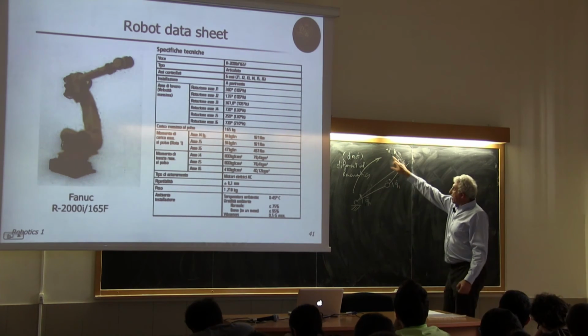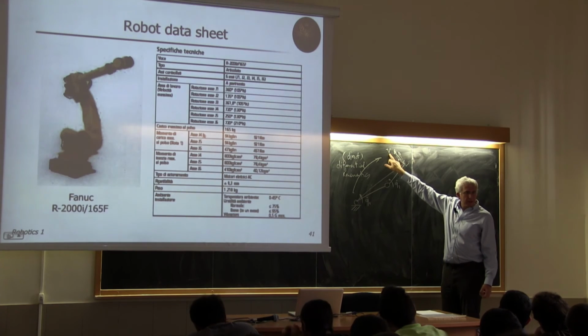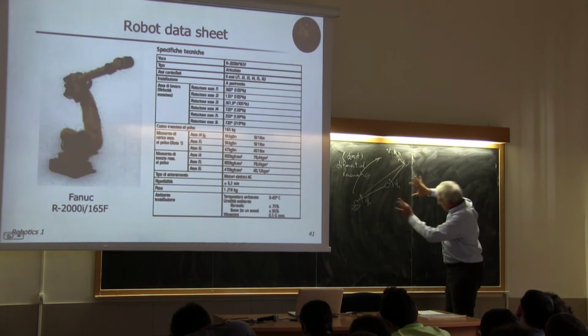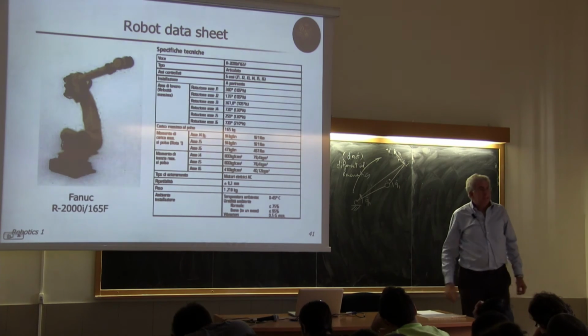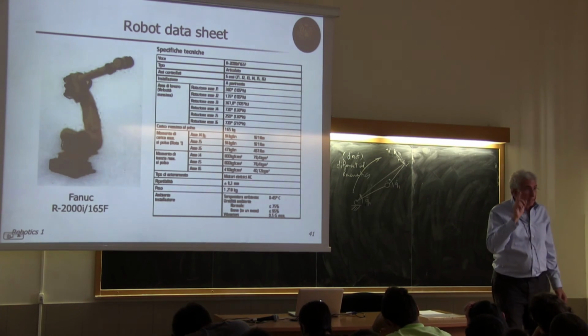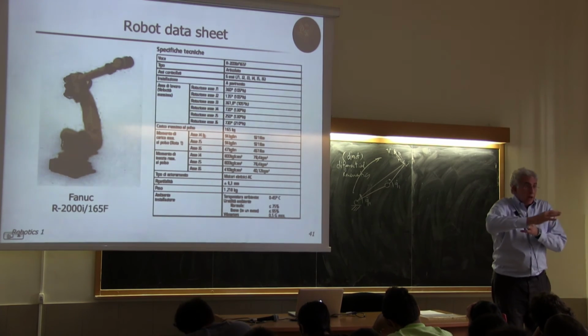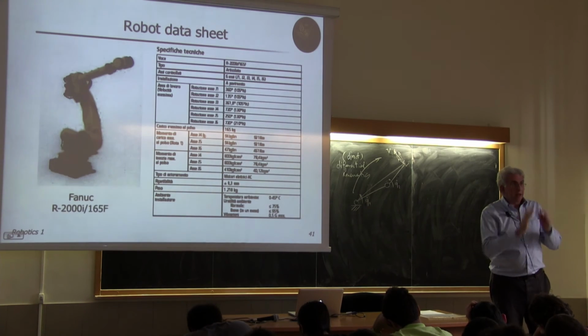Exactly. I'm given a desired velocity here, and I want to compute the two joint velocities that realize in this configuration that instantaneous velocity. Remember, instantaneous, because once you apply this velocity, the configuration of the arm changes and you have a new problem. So this is just at some instant.